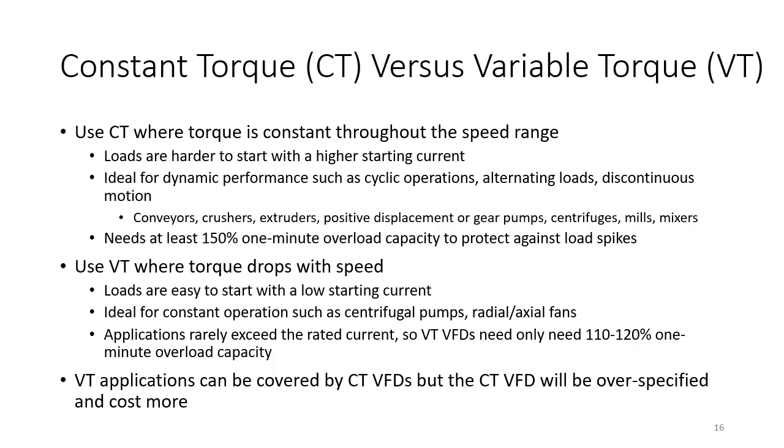CT has its place. If you're not sure, use a CT, but if you've got the wrong type of application, it will be overspecified and it will cost you quite a lot more to buy. Running costs, not so much. It's normally about that startup cost. And in terms of that difference in price, in my experience, a CT VFD is about twice the price of an equivalent VT VFD for the same sort of load of motor. So quite a big difference.